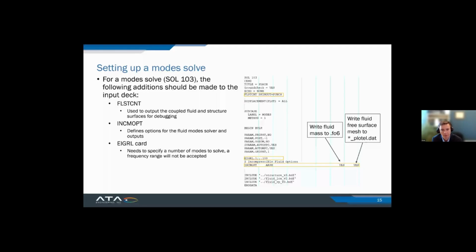For launch vehicles, from rockets up to small missiles, that gets into the realm of what you're interested in, so it kind of depends. If you're looking for a rule of thumb, I don't have one for that. But supposedly, you can look at your modal effective mass of how much fluid will actually be moving around, and then you make a decision on whether or not that's relevant.